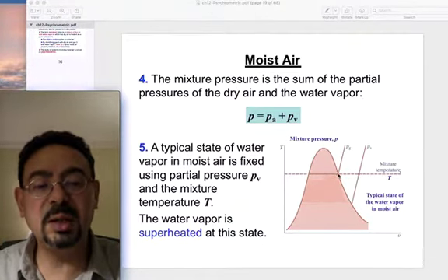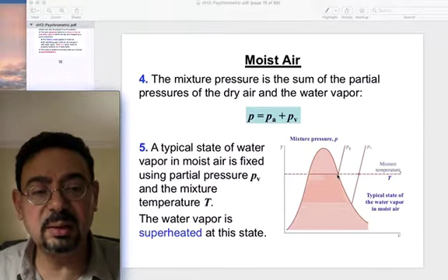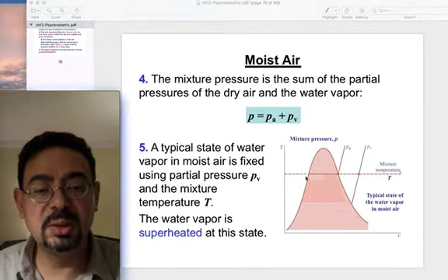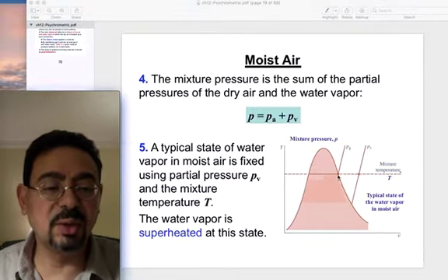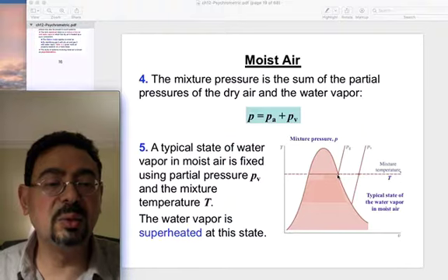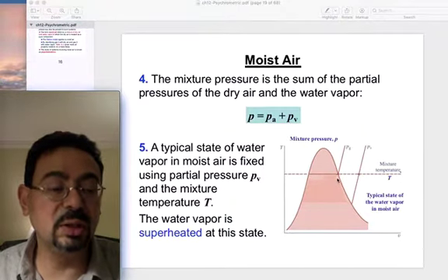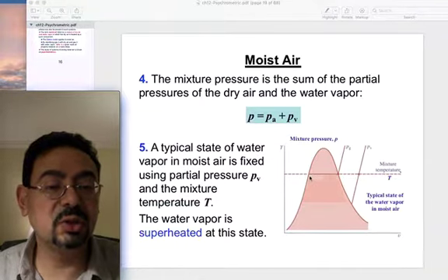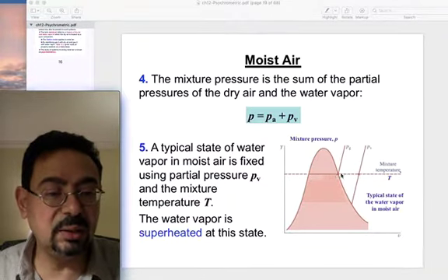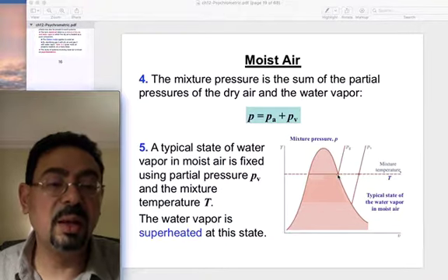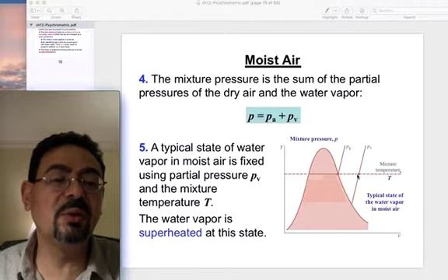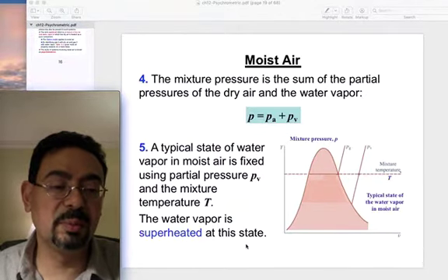If the water vapor is sitting over here, what is that? Remember the T-S diagram? So this is saturated liquid, this is saturated vapor, right? Like if I ask you to calculate the h here, you'll go to the steam table and get h, what? h g. And here you will get h f, right? So that is saturated vapor, right? So he said that for most applications, the vapor pressure will be sitting over here. So it is usually superheated vapor, right?